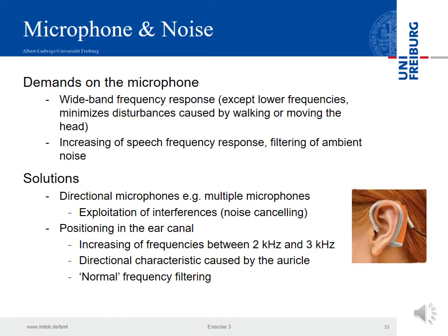It's relatively high, so we need a wideband frequency response, but blank out lower frequencies to suppress movement artifacts and vibrations, for example by walking or moving the head.